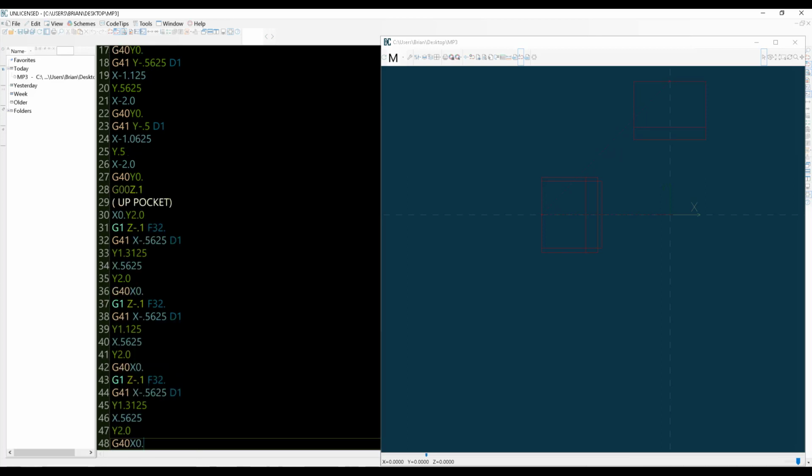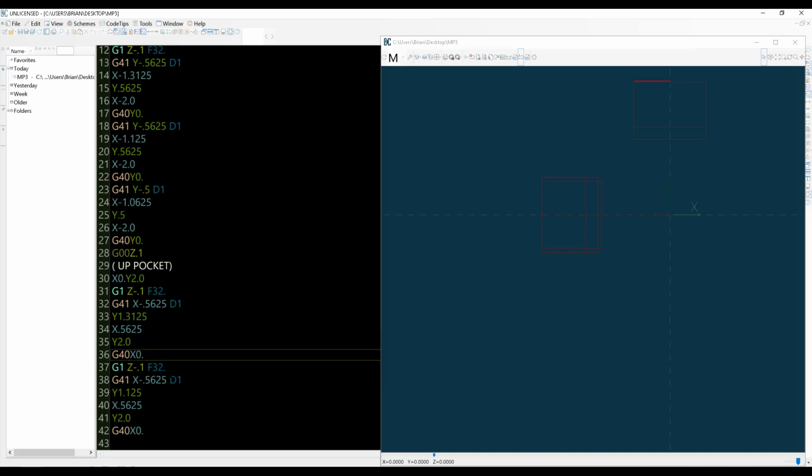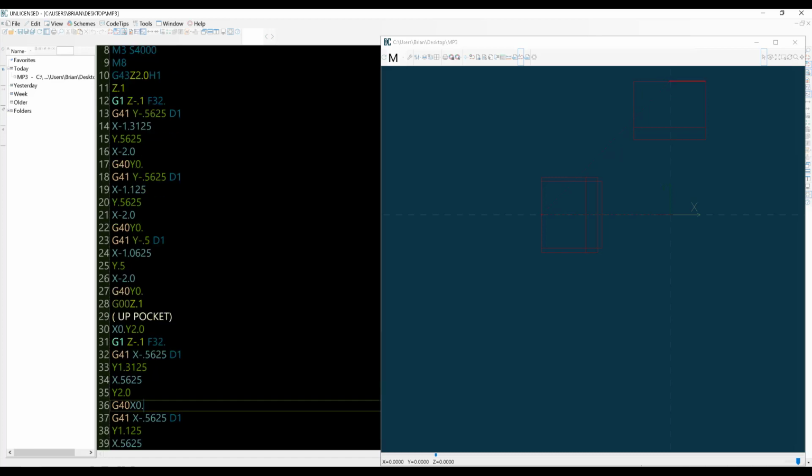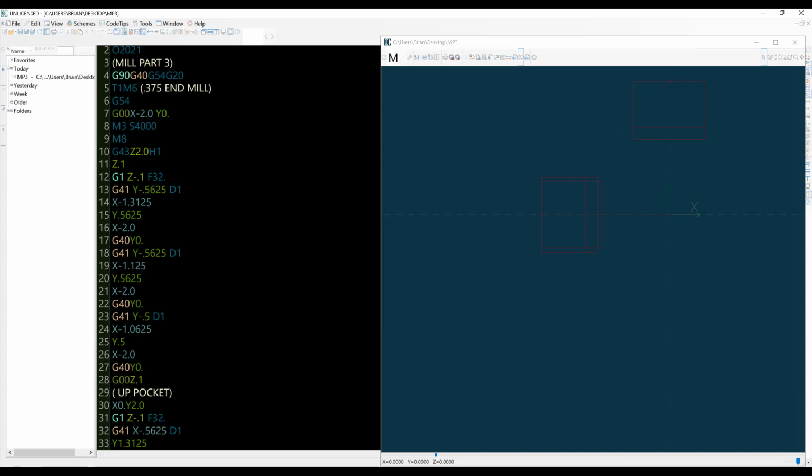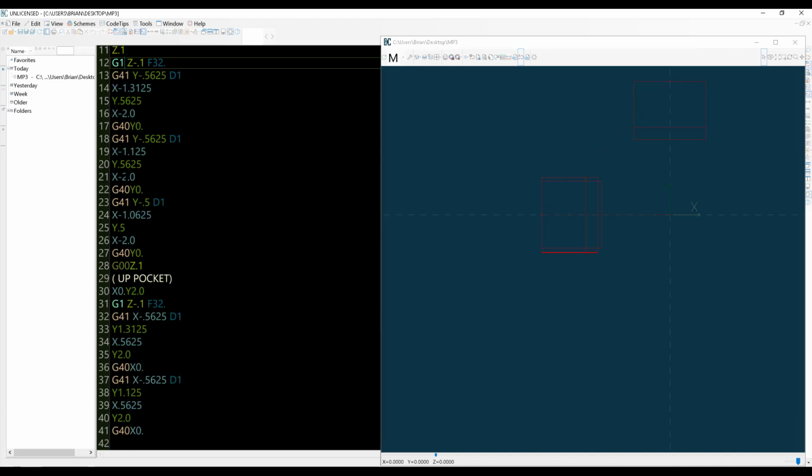and this is going to go to, we got to make a couple changes here. Okay, so we can't really paste that again. Why? Because we changed to Y0.5. So let's delete that next step. Okay, should be right around here. And also, we really don't need our Z minus again. So we can get rid of that too. That's not going to change us here. Okay, I don't think I copy and pasted up here. We have our Z.1. We don't have it again. So that was a mistake on my part. So we are good here, we are good here, we're good here. Everything looks okay for our first two cuts.